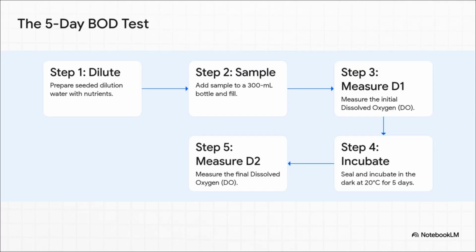So this is the classic 5-day BOD test procedure. We take our sample, dilute it with special water that has nutrients and some seed microorganisms to get things going.